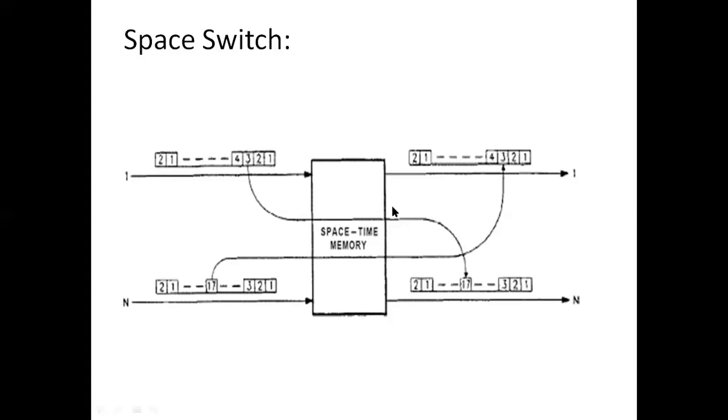Only the change of slots takes place. The slot that is supposed to be transmitted at that particular point of time will assume the slot content of one of the incoming PCM highways. The transfer of a slot into a different slot takes place at that particular instant, with no difference in time. That's the major difference between time switching and space switching.